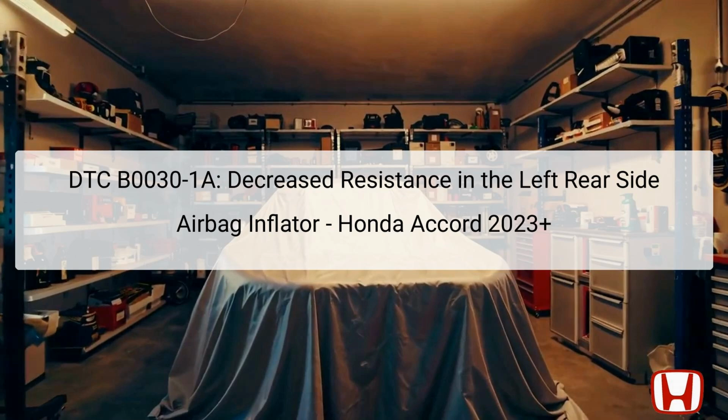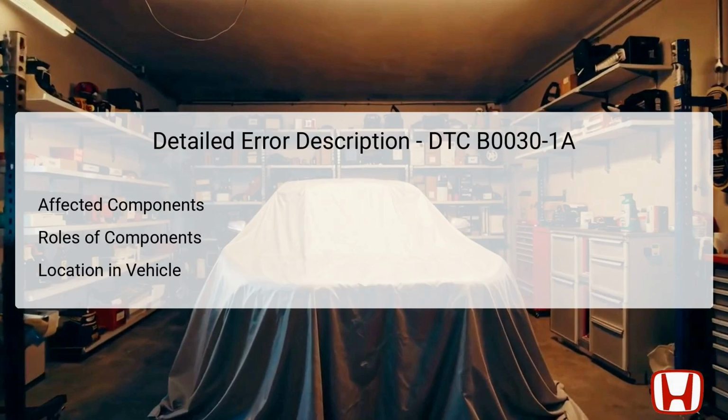passenger safety. The SRS, Supplemental Restraint System, unit monitors various airbag components, and when it detects lower than specified voltage in the inflator circuit, it will trigger the DTC B0030-1A. Proper diagnosis is essential to ensure that all airbag components are functioning correctly and that the vehicle is safe to operate. This guide will outline the error description, possible causes, symptoms, and detailed troubleshooting steps to resolve the DTC effectively.